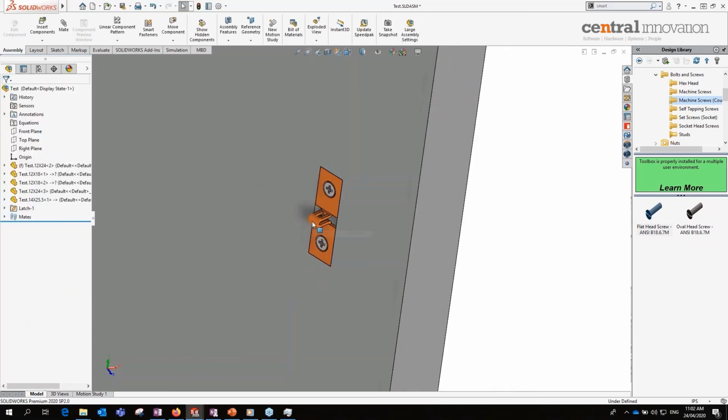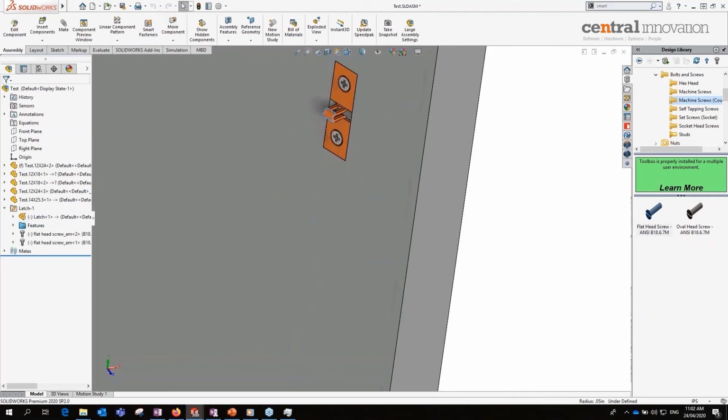The smart feature is attached to the part, so once you move it and rebuild, it will be updated automatically. So you can imagine for all the structure systems, for all the connections for your structure members, you can build your smart connection with all the holes, fasteners, and everything. And all you have to do is just drag and drop, and all the holes and fasteners will be applied automatically. And if you modify the connection position, all the holes and fasteners will be updated automatically as well.